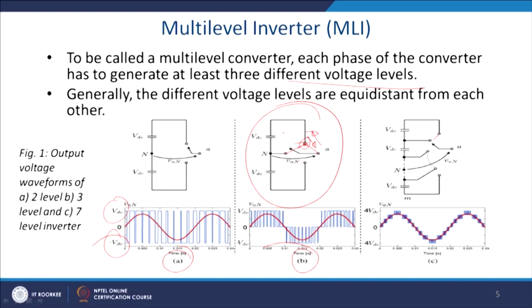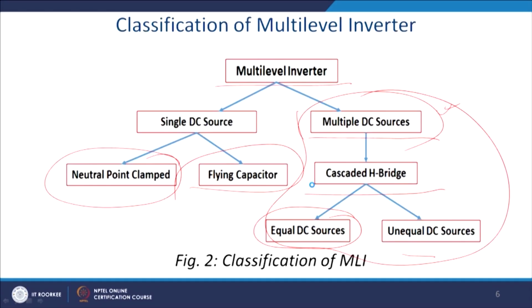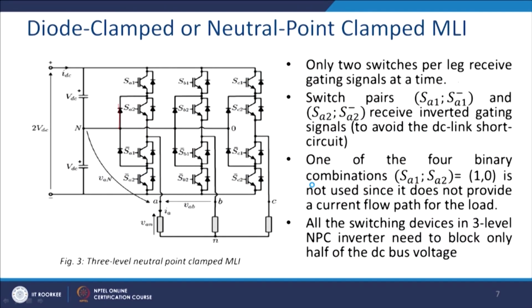Same way, when you put this switch here, then also you are blocking the voltage of minus VDC by 2, plus VDC by 2, and the current can be bidirectional. Same way, the upper one will be just a replication of the reverse one, just changing sign. So, how can these features be incorporated in the circuit we discuss?